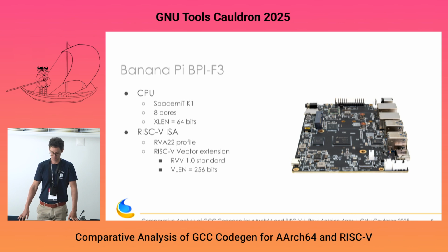Here for reference, I'm giving you the specs. What is important is the vector length that I mentioned earlier, 256 bits, and also that it complies with the RISC-V vector extension standard 1.0, which is the one that's been frozen and ratified. There were earlier designs, but they complied with an earlier version of the standard. So this one is the one that matters.